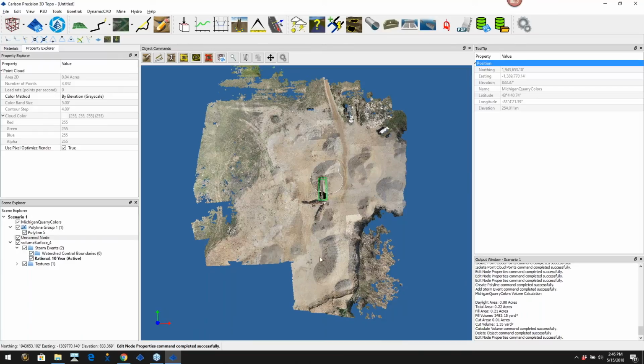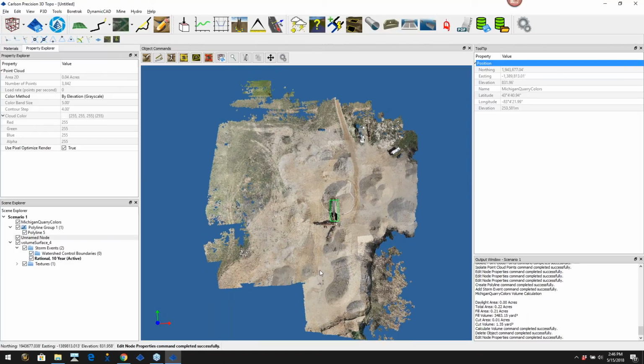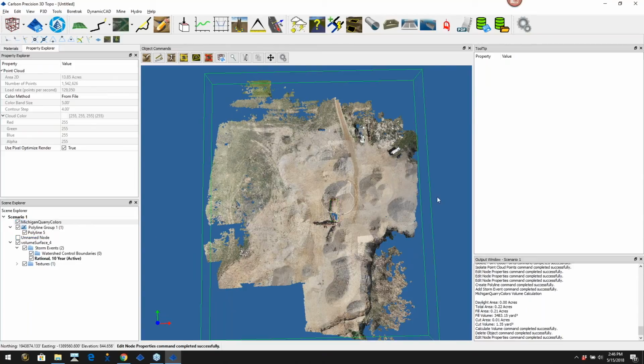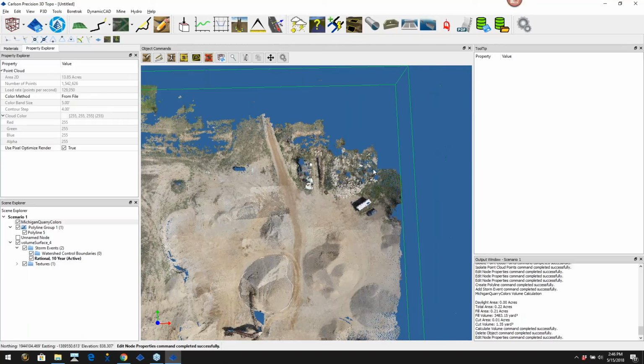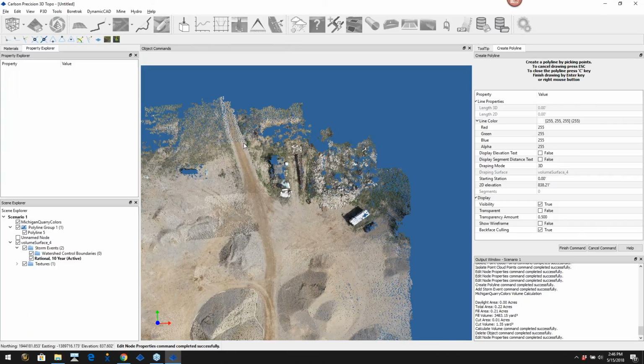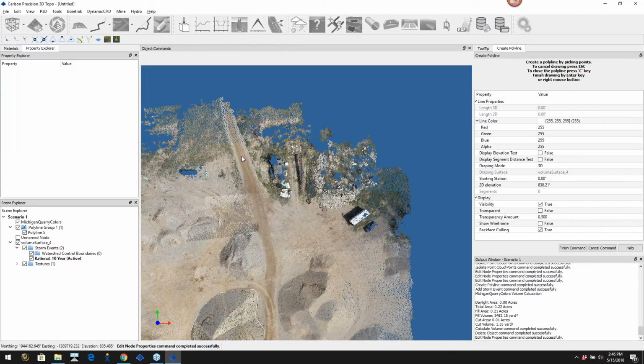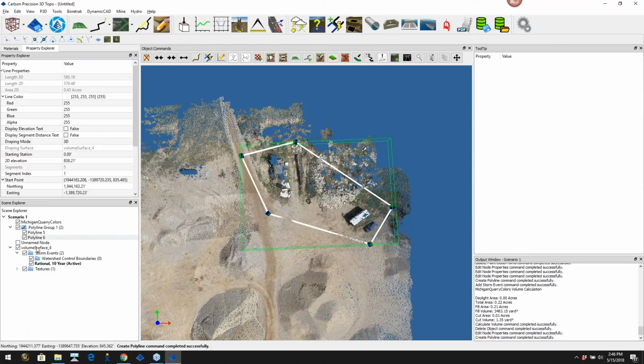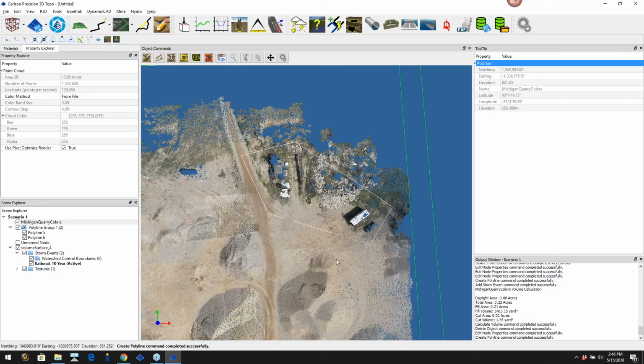No, I think that you've shown the bare ground filter, at least a small example of it, which works really well against trees and vegetation. And the nice thing about our point isolator and the way that you can split clouds up and work by polygon areas is that you can do more aggressive processing in areas where you have high density vegetation, to clean the cloud up in there, but then be less aggressive where there's not any noise or vegetation, so that you maintain a higher degree of accuracy. So we have a really good, easy to use mix of tools to allow you to pretty quickly go in there and do just exactly that.